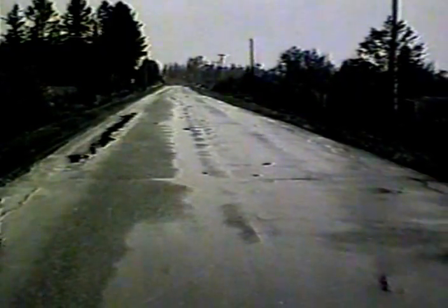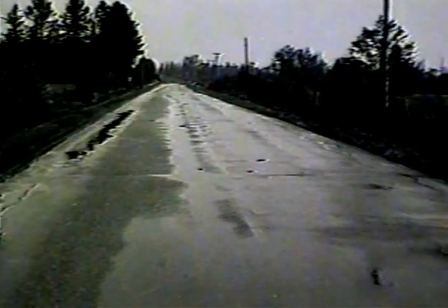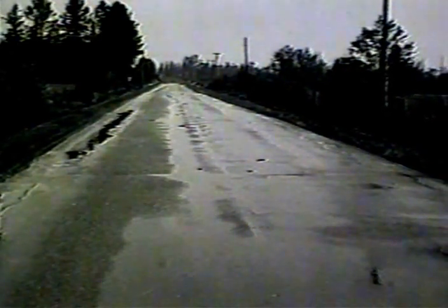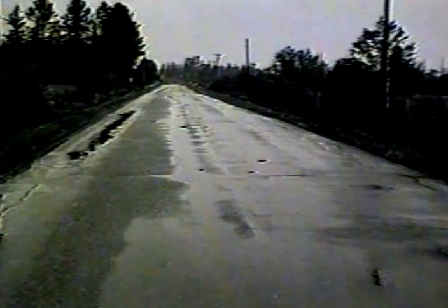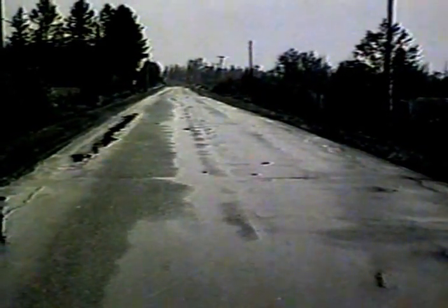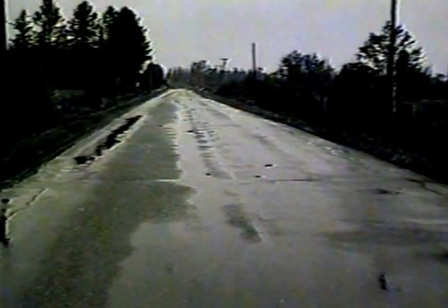Next, let's move on to surface deformations. We'll talk about rutting, shoving, settling, and frost heaves. Rutting might first occur in the wheel pads. It might be fairly shallow in nature, only a quarter or half an inch, and you might only be able to see it after a rainstorm when you see water collecting in the actual ruts.